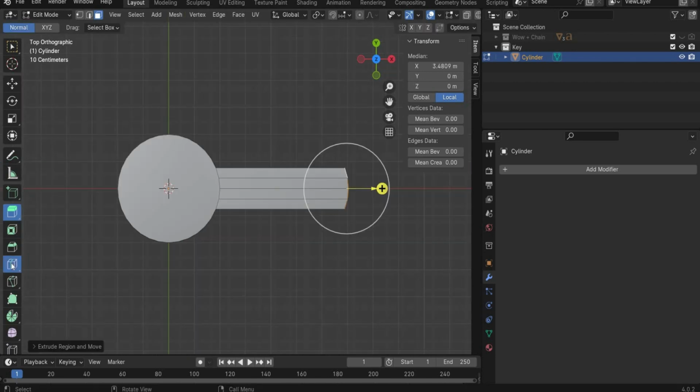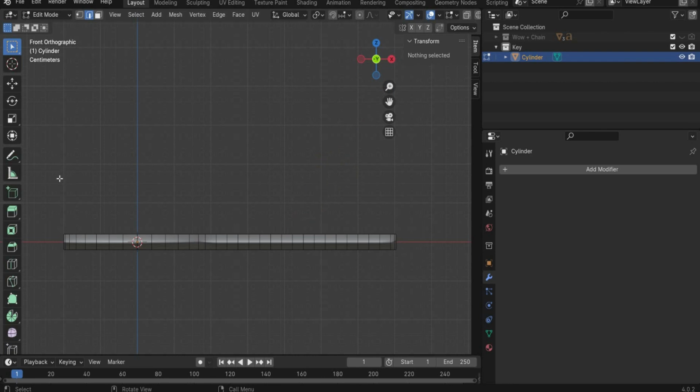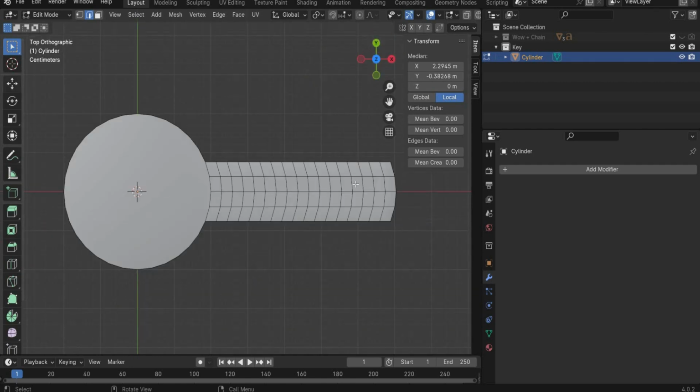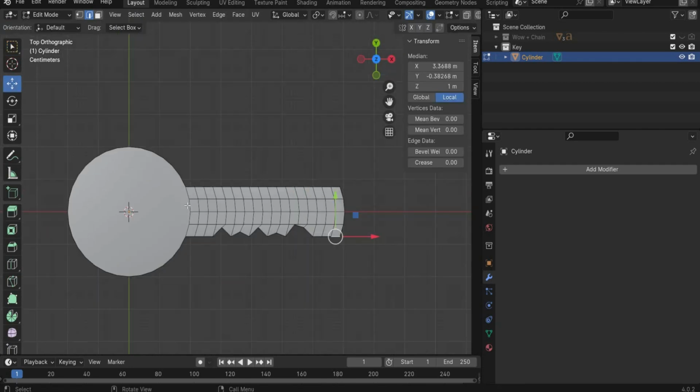Alright, in the next step, choose the loop cut, set here a cut around 16, rotate it again, select here some points, hold shift, bring it up again, and bring it here inside. Yeah, something like this. Alright, now we create the typical holes here on the key.